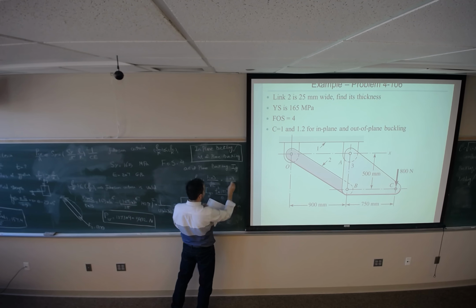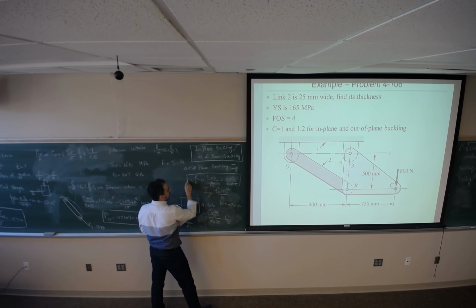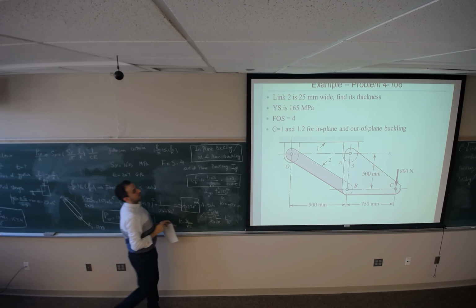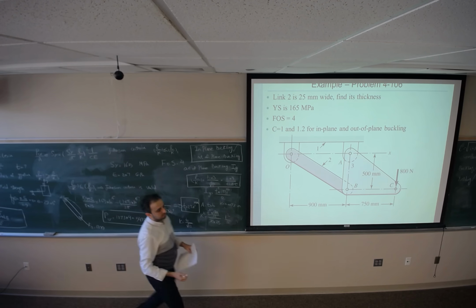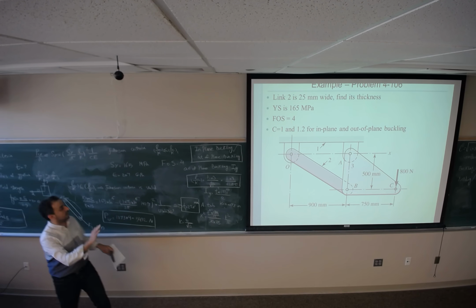So the value that I will get is going to be 1.03 divided by 0.289 times T. It depends on T. If you calculate L over K, the only thing which is different from the previous case is C, because E is the same, pi squared and SY would be the same. 157.4 is going to change to something. 1.5 or 1.2? 1.2, thank you. Not 1.5.